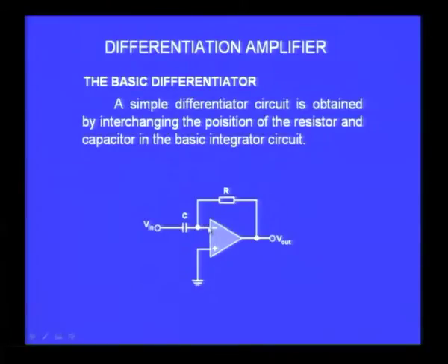I will explain in more detail what the input bias current is all about later on, but for the moment imagine that the current actually passing through the amplifier is going to be very, very small because of the large input impedance of the amplifier.